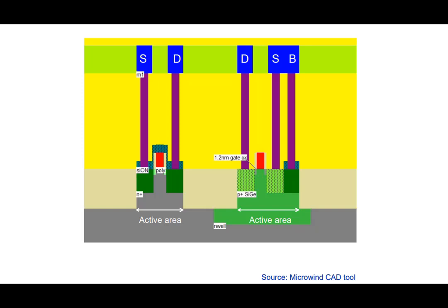It shows you both an n-type and a p-type transistor. So we are talking about a CMOS inverter, so it shows you both of them. Note that the gray region that you see here is all silicon. You can see N plus here, and you see the gate here in red. Whenever you see red, it is usually polysilicon.